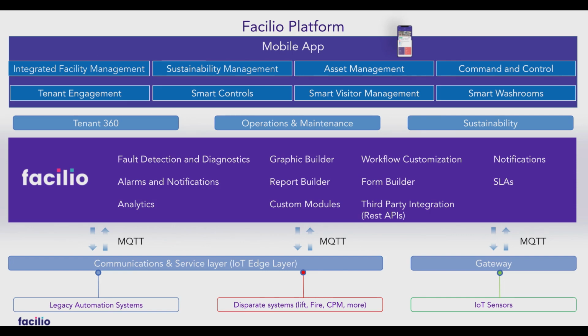into three main layers. The bottom layer here is the data aggregation piece, where we're interfacing with the various assets within the building in the various automation systems. So this could be the HVAC systems connected to a BMS. There might be disparate systems, which could include the fire safety, access control systems, and so on. There might also be IoT sensors present within the buildings for use cases like air quality monitoring, people counting, and so on. So all this can also send data to the cloud.